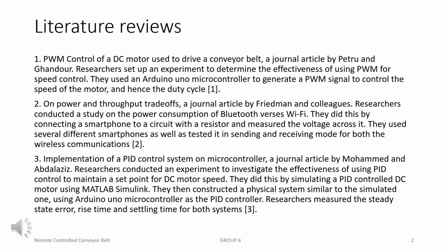They then constructed a physical system similar to the simulated one, using an Arduino Uno microcontroller as the PID controller. Researchers measured the steady-state error, rise time, and settling time for both systems. They concluded that both systems were effective and managed to meet the requirements of having a steady-state error of less than 5%, rise time less than 2 seconds, and settling time less than 4 seconds.